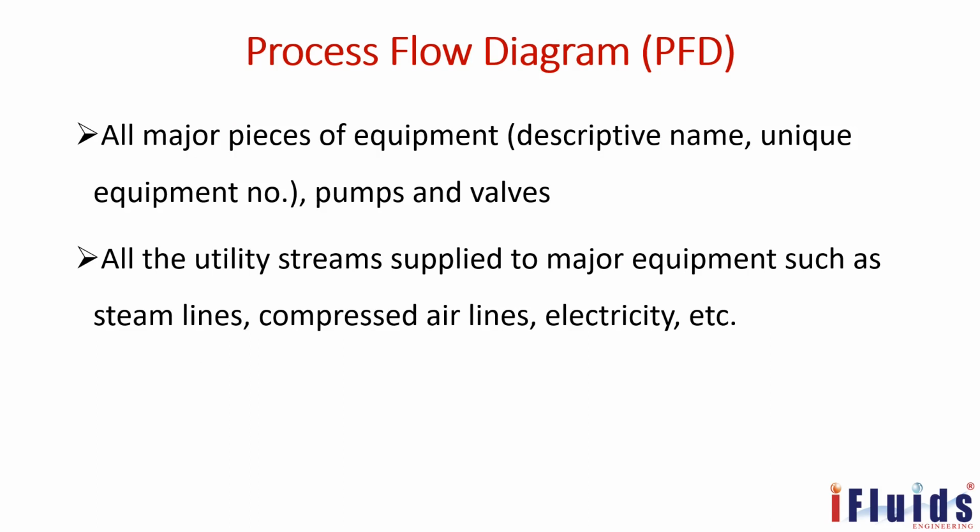All major pieces of equipment, with descriptive name, unique equipment number, pumps and valves. There are pumps and valves, also rotating equipment. Major valves we have to show. Minor valves, minor isolation valves, we need not show in the PFD.